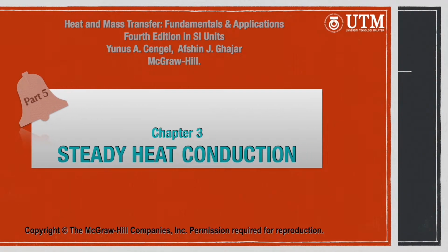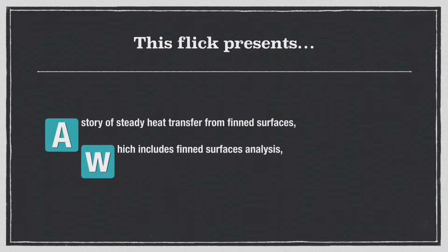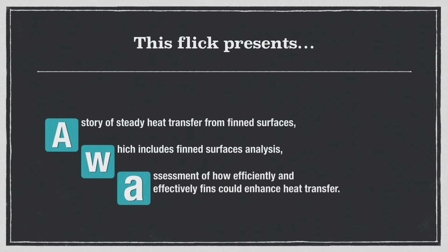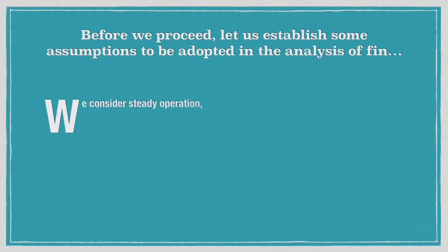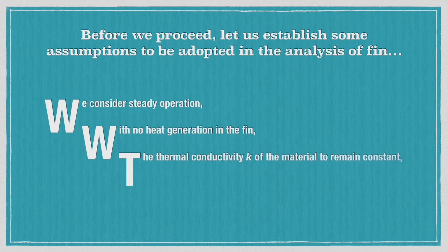Steady heat transfer from finned surfaces, which includes finned surfaces analysis, and assessing how efficiently and effectively fins could enhance heat transfer. We consider steady operation with no heat generation in the fin, the thermal conductivity k of the material to remain constant, and the convection heat transfer coefficient h to be constant and uniform over the entire surface of the fin for convenience in the analysis.